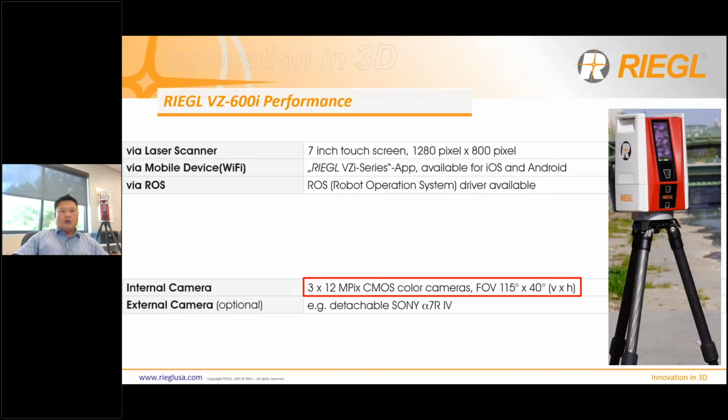But when you scan anywhere, you never scan from one position, right? Especially when you're scanning indoors in a tight room, such as a mechanical room, with line of sight. There's no way you're going to scan from one or two positions. In fact, in a mechanical room, I can see you scanning a dozen scan positions or more. And if you do move it, most likely, guaranteed, you're going to cover the overhead, and that's your concern. So it shouldn't be.